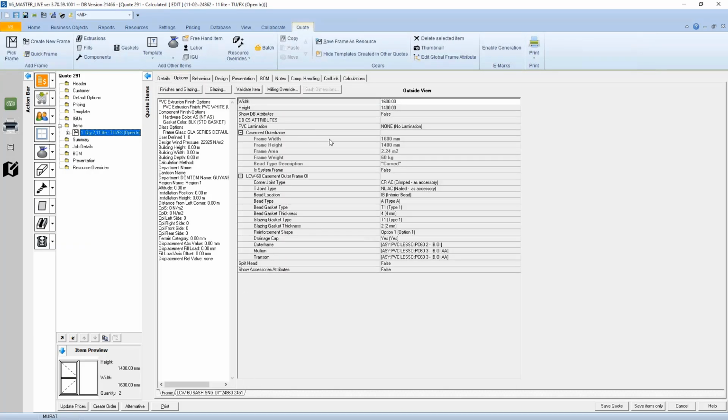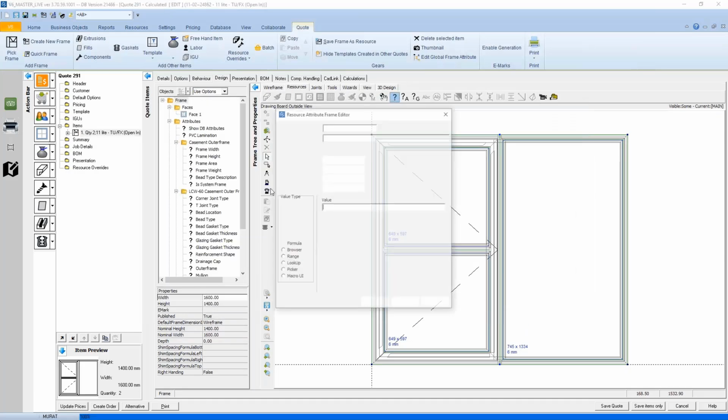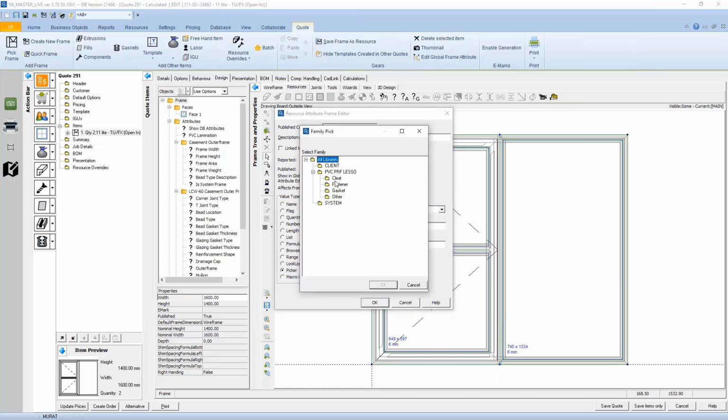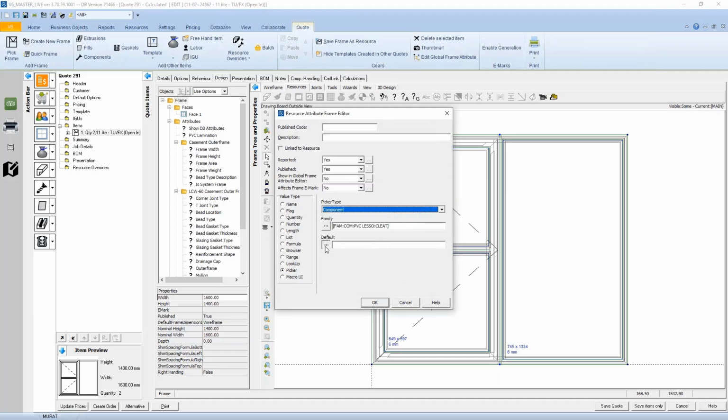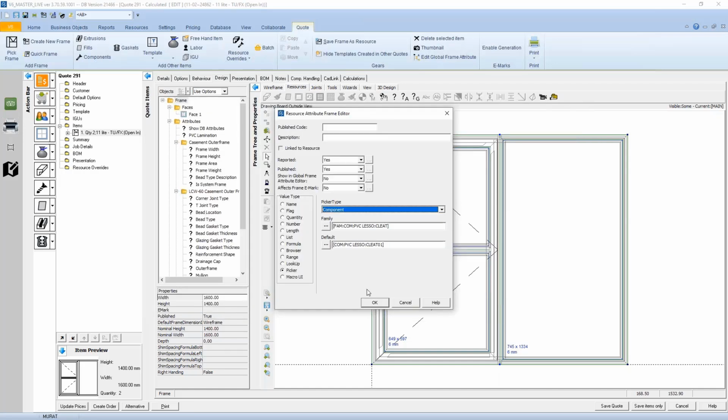Yeah, if you were using a picker type of attribute, then in the picker attribute we can default the value to a certain one. So if I just add a new picker attribute here, I guess what he means is that I have a picker attribute here, which is a component type hardware, and it lists a certain family, and then from there I can say, okay, this default value will be this.